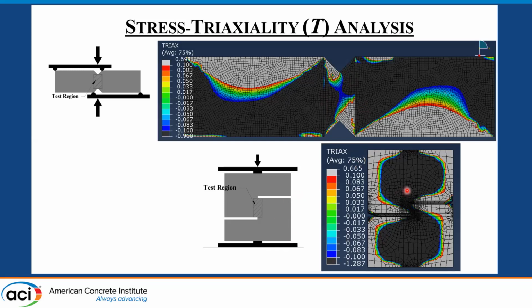The S0 geometry, again, the same phenomena. We expect the shear formation or shear stress state formation in between the two notches, but as you can see in the FEM, that's highly under compression. The black shade is nothing but high negative values, more than 0.1 and more than negative 0.1. So that is in compression, and the white part is in tension.